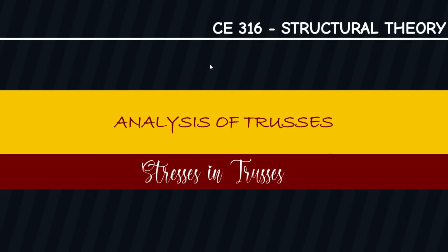Generally, all the loads in a truss act, or are assumed to act, only at the joints. Thus, it follows that all members of a truss are assumed to be two-force members which are subjected only to direct axial stress, that is, either tension or compression. A truss is completely analyzed when the direct axial stresses, kind and amount, in all members have been determined.